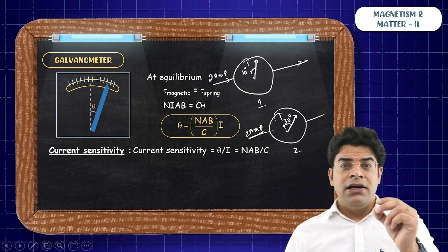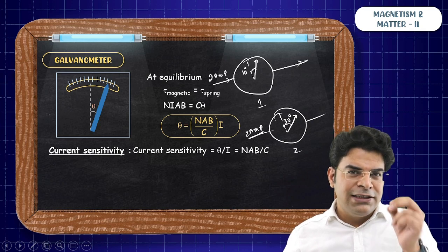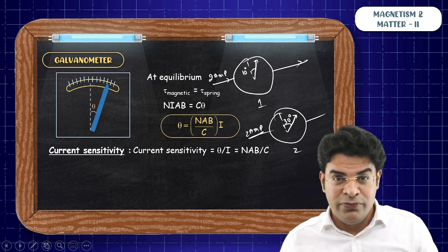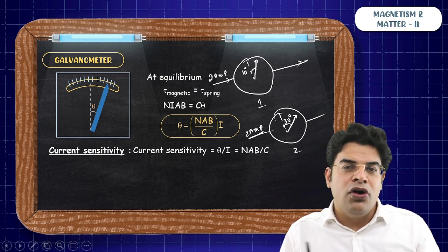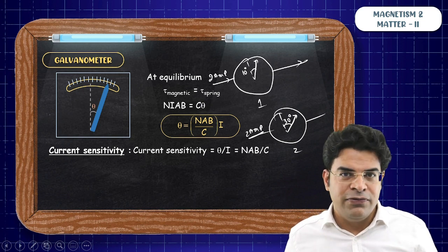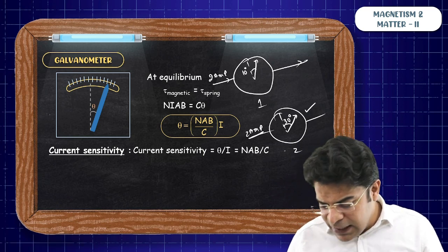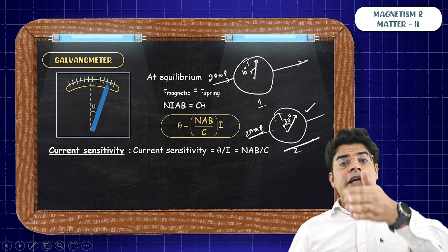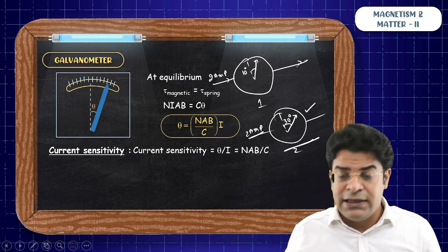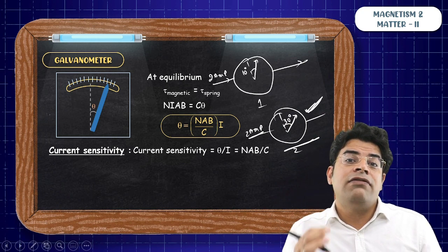So which galvanometer will you say to be more sensitive? Sir, a person is said to be more sensitive when they show more output for the same input. If I crack the same joke on two friends and one of them gets very angry, we will say that friend is very sensitive. Similarly here, on driving the same current in the second galvanometer, the angle of deflection is 3 times. So you will say that the second galvanometer is 3 times more sensitive for current than the first galvanometer.